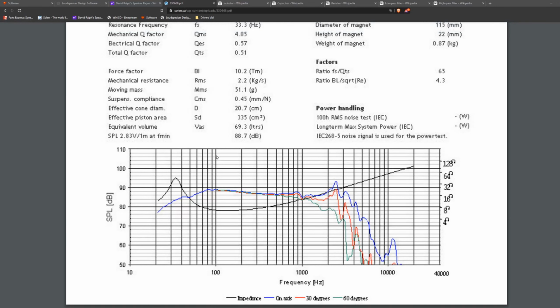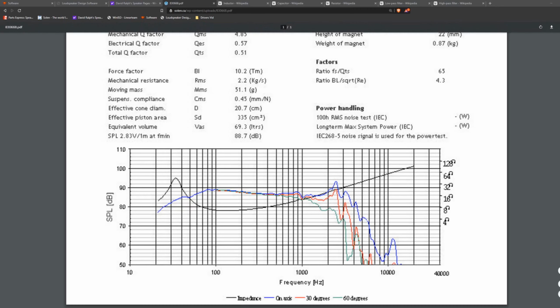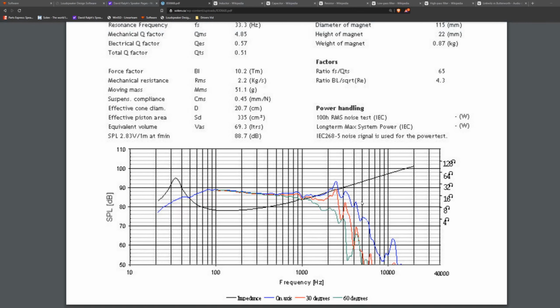The second driver will be a mid-range driver, and the third driver will be what is known as a tweeter, or the higher frequency driver. Speaker crossovers are typically not an iron gate transfer from one to another. Typically there's some form of slope involved. And for this reason, the mid-range driver, even if it's crossed over to the woofer, can actually assist in frequencies below the crossover point, increasing the tolerance for the potential loudspeaker system, creating a more flat and level sound.